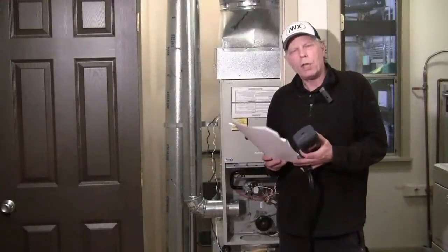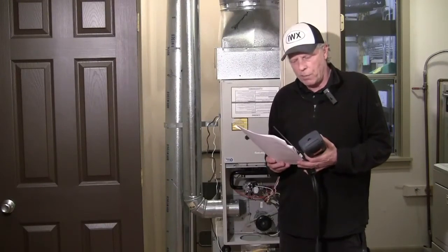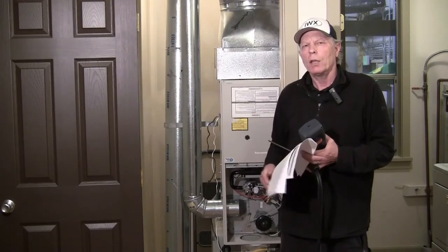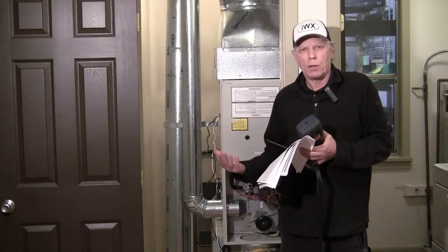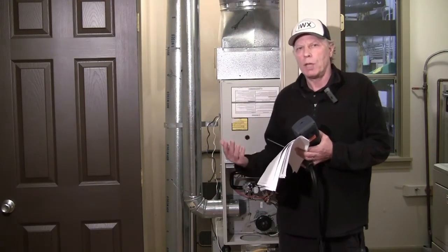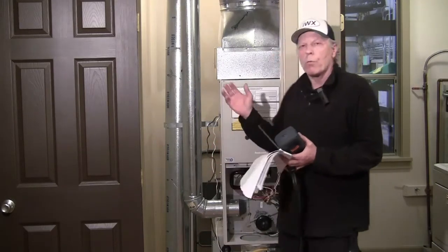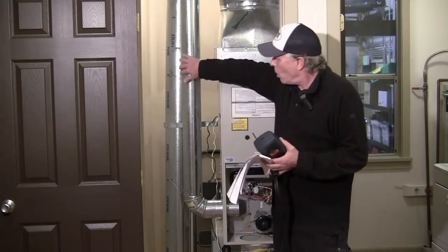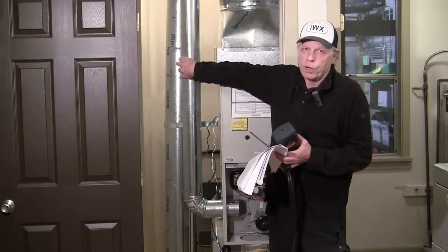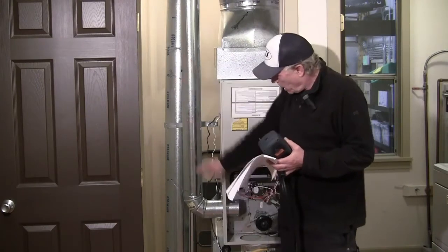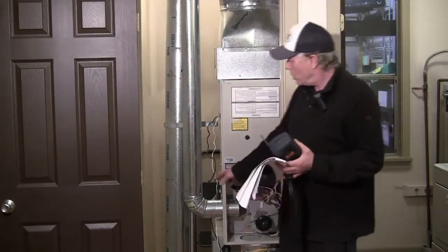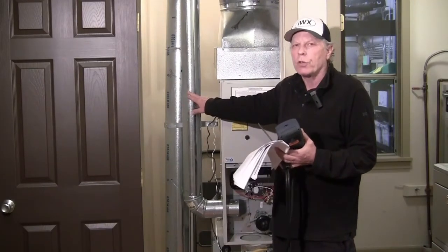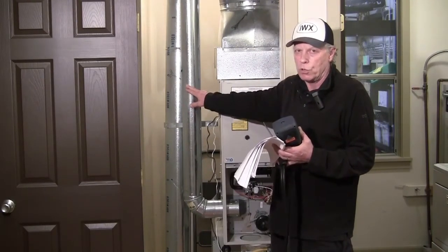We're on line 3. And this is where the candidate's required to measure CO in the heating system flue gases. Again, this is about where to take the measurement and at what time to take the measurement. We're going to run this furnace for 5 minutes, and we're going to take the CO, and we have a hole in the flue over here to take the CO measurement. This is an 80% efficient furnace, so that's the least diluted sample we can take. All right, and we're also going to take our efficiency measurement there too.